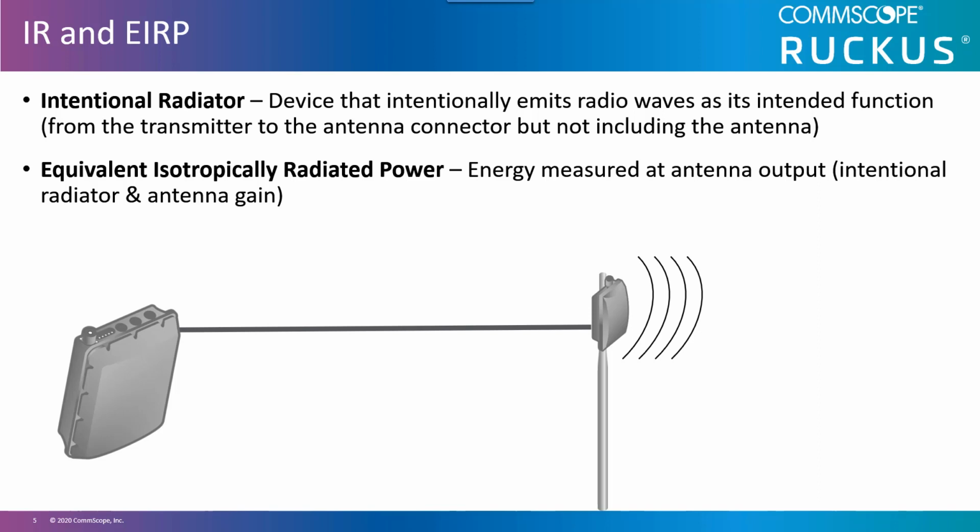In a wireless LAN transmission system, this is the point at which the antenna is connected to the radio or to the cable that leads to the radio. The RF signal from the transmitting radio may pass through connectors, cables, attenuators, amplifiers, and lightning arresters before it even gets to the antenna. All of these components impact the signal before it arrives at the antenna.